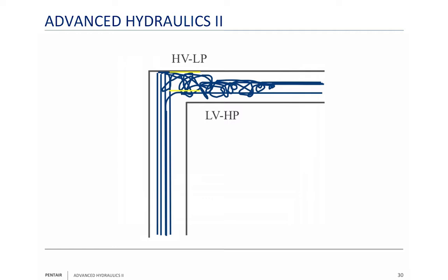If the water is moving through there so fast and the velocity is so high, the pressure will drop to the vapor pressure point of the water, and you are going to get cavitation. So you'll get a vapor bubble in there. Now, of course, where does the vapor bubble go? If you follow along here, you can see it's moving right to the outside edge of the pipe.